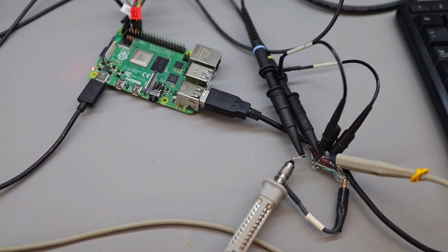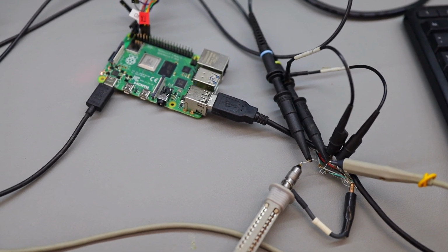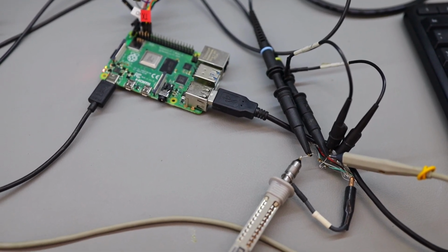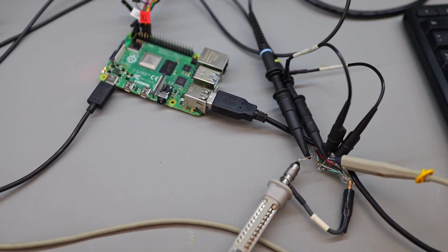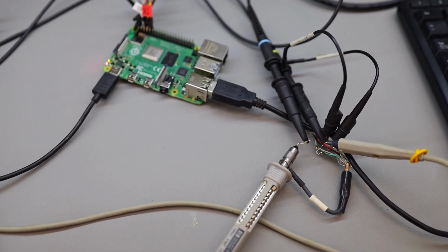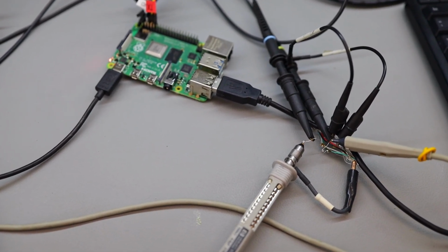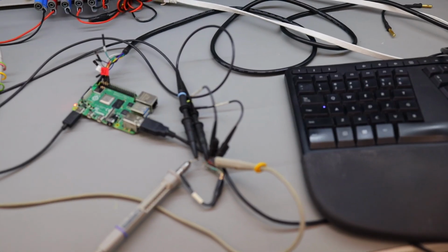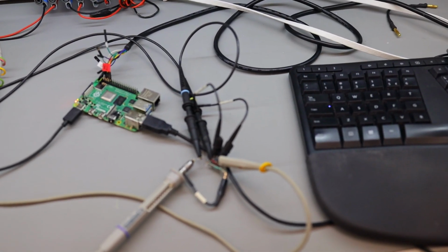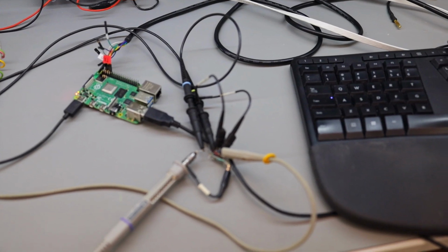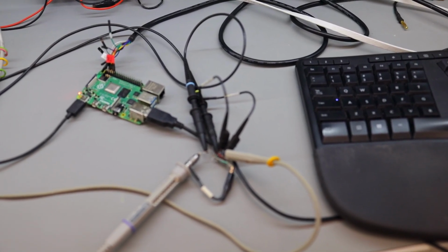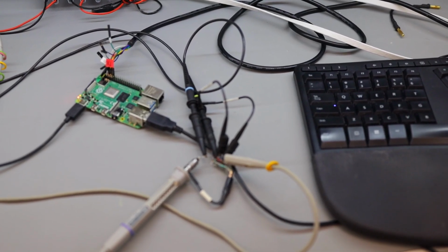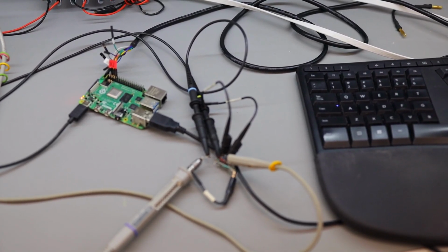So let's get started. This is our setup. We're going to use a Raspberry Pi, and right now I have removed the insulation from the USB cable, and there are 4 probes connected, 2 of my MDO 3000 because my MDO 3000 also can decode, and 2 of the probes belong to my MSO 804A. And right now it's connected to a keyboard, and keyboards are generally very, very low speed devices, so they use only USB LS, and that is perfect for our scenario. We will try to find out, when we do a key press, if the data gets detected onto the screen.